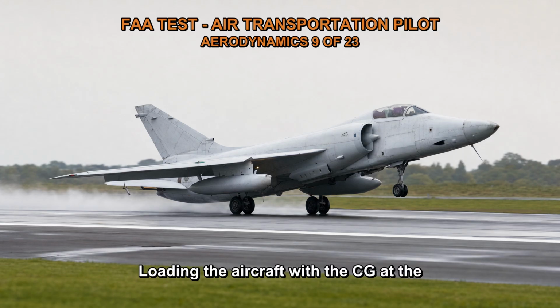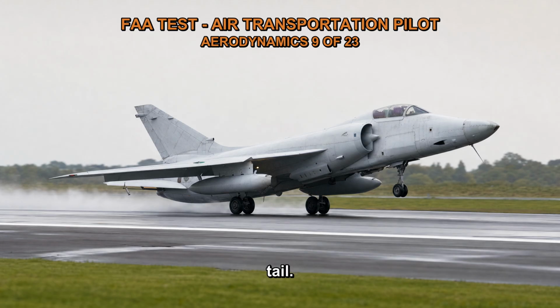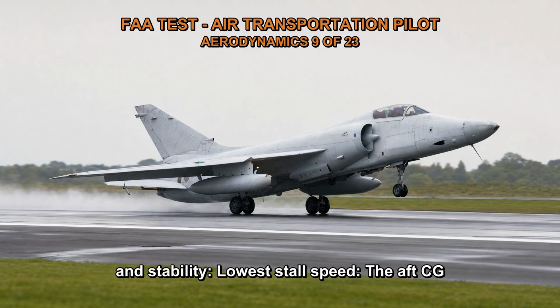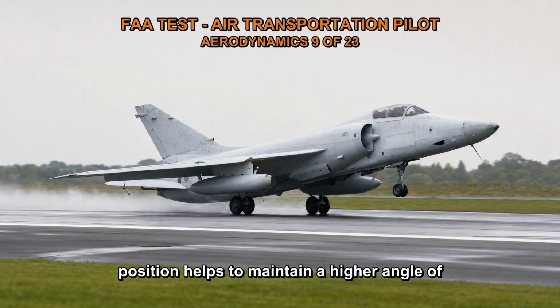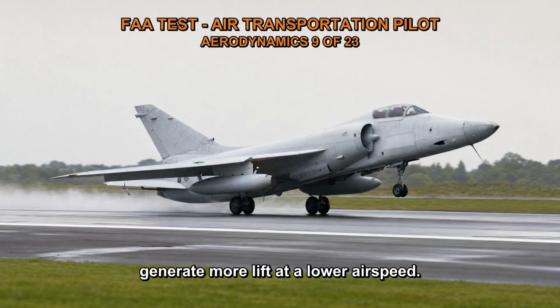Loading the aircraft with the CG at the aft limit shifts the weight distribution towards the tail. This has several effects on the aircraft's performance and stability. Lowest stall speed. The aft CG position helps to maintain a higher angle of attack during the stall, allowing the aircraft to generate more lift at a lower airspeed. This results in a lower stall speed.